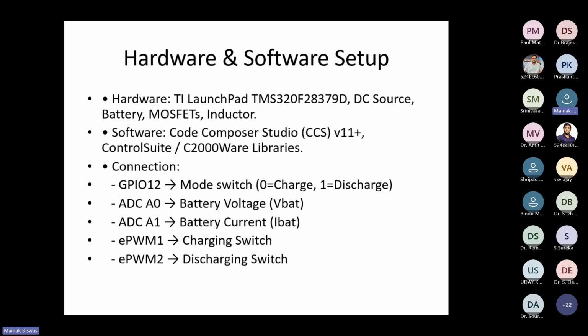Then in the hardware and software setup, for the hardware we'll cover the TI LaunchPad, whatever we discussed yesterday or the day before, F28379D, the DC source, the battery, the MOSFETs and the inductors. For the software part, we'll use Code Composer Studio, that is CCS, and in my case I am using version 11, and the control suite.